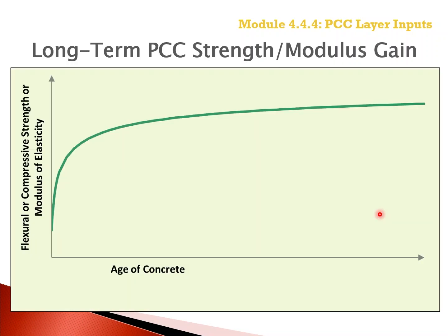This slide includes a graphical illustration of the increase or growth in the elastic modulus and flexural or compressive strength of the PCC mixture. The data sources used for this growth function or for model development were extracted from the LTPP SBS2 experiment, from which over 470 test results were available for use, the long-term Portland Cement Association study conducted by Wood that included 210 tests, and the actual road test, which included 15 tests or mixtures.